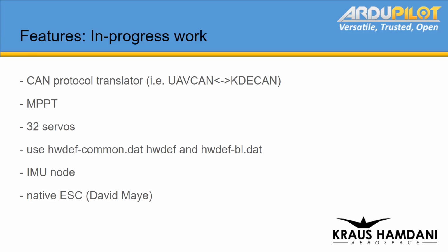So FOC is, I think, a very worthwhile feature to have, but I wouldn't want it to be required, as in the only option. That's been one of the weaknesses of some ESC firmware, being only FOC, which can be quite difficult to tune and get working on different combinations of motors. So having trapezoidal as the base, but then optionally FOC, is there any particular reason why that wouldn't be doable, Leonard? Well, the reason why I like VESC is it does exactly that. You can set it up as trapezoid or FOC.